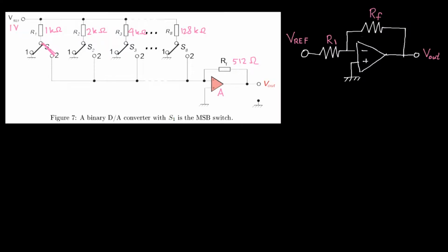Because the gain of this operational amplifier is not infinite in this question, we need to assess what the potential will be at this inverting terminal. For that, we can use the basic equation of the operational amplifier. The output voltage of an operational amplifier is the gain A multiplied by the difference that is sensed between the positive terminal and the negative input terminal of the operational amplifier.